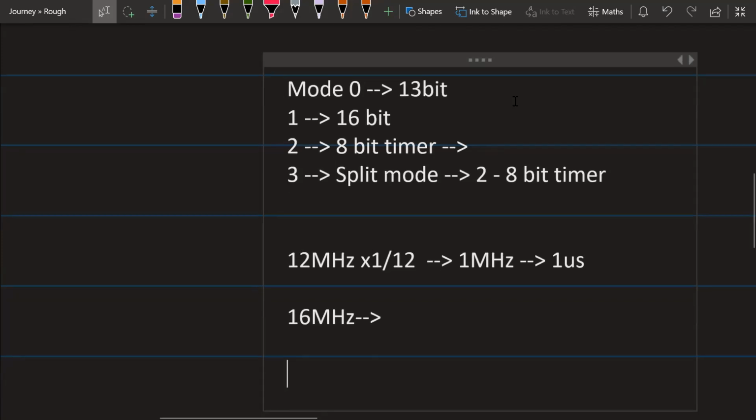So we got to know how to control the timer using TMOD. But if, for example, this timer reaches certain counts, or I'm using this timer for monitoring some time, like 1 millisecond, or monitoring some interrupt, then I need to have some output register also, where I have to monitor. For that, we have the TCON register.